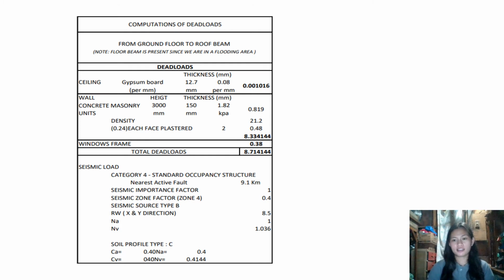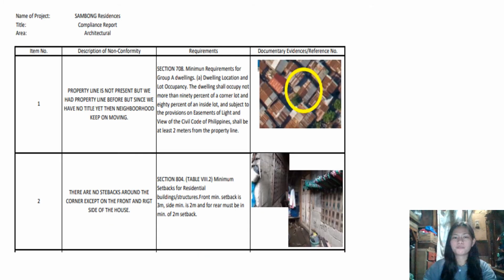So, ayan na guys. After na-discuss natin yung floor plan ko, yung architectural at structural, let's proceed with the design. Before I design, using the STAAD Foundation, STAAD software, I first computed the dead loads, or the loads that we needed for the design. I got this from the National Building Code of the Philippines. Nandun lahat, kinuha ko lahat ng equivalent nito, even for the seismic load. So, ayan, na-check ko na yan lahat, na-input ko na yan lahat.